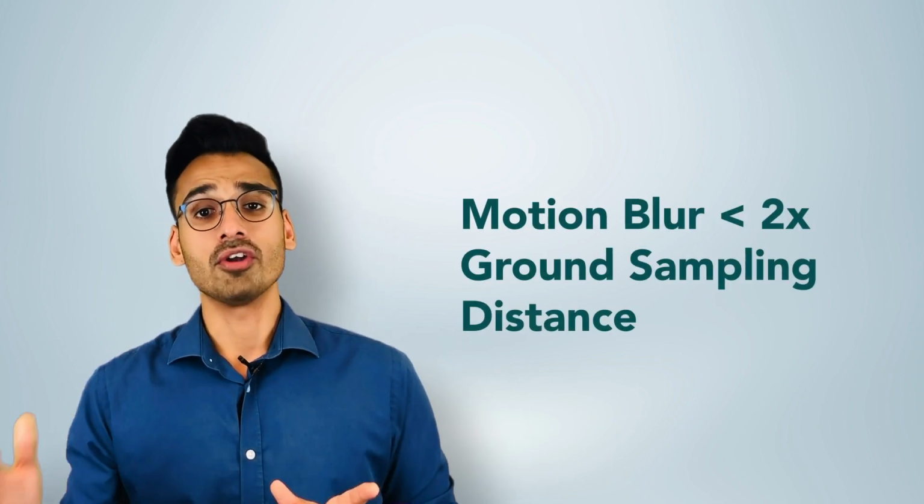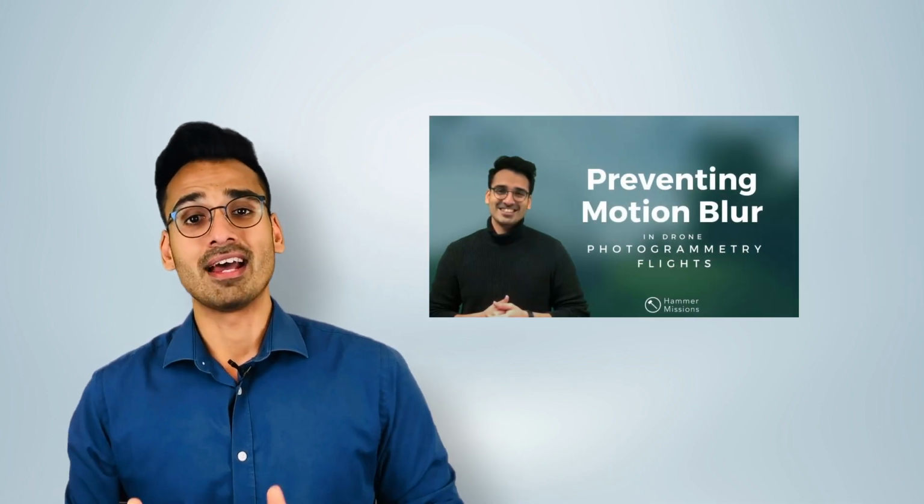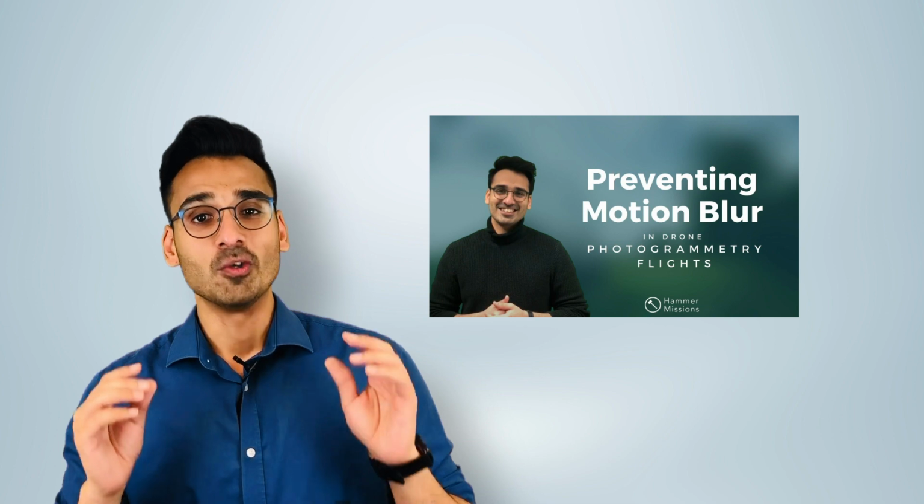Maybe you're not able to completely eliminate motion blur, but you may be able to minimize it. But what's really important with motion blur is that you need to make sure that your motion blur is not 2x your ground sampling distance or more, because if that's the case, then whatever you're processing, your map or model, is not going to have the same level of quality at the end, and you're going to experience certain objects not looking as good as you expected. So again, GSD and motion blur are correlated. It really depends and matters whether or not you have used the right GSD given the right job.